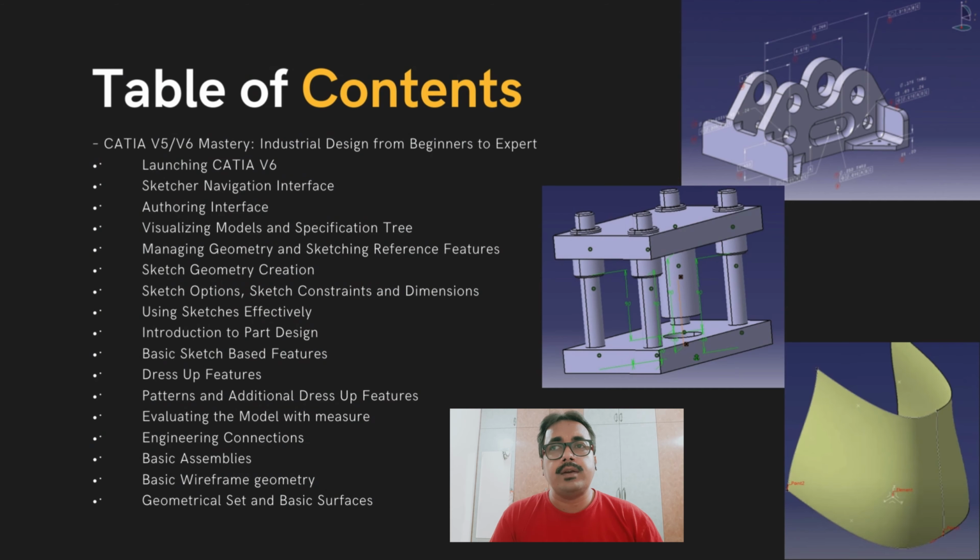Then patterns and additional dress up features. You need to learn how to create the patterns inside the part modeling, and use the dress up features in that to enhance your design. Next, I'll be coming to the evaluating of the model by measuring. There are measure tools, like you can evaluate your model, which is very critical, like dimension, weight, surface area, whatever. And we'll cover how to evaluate the model using these measuring tools.